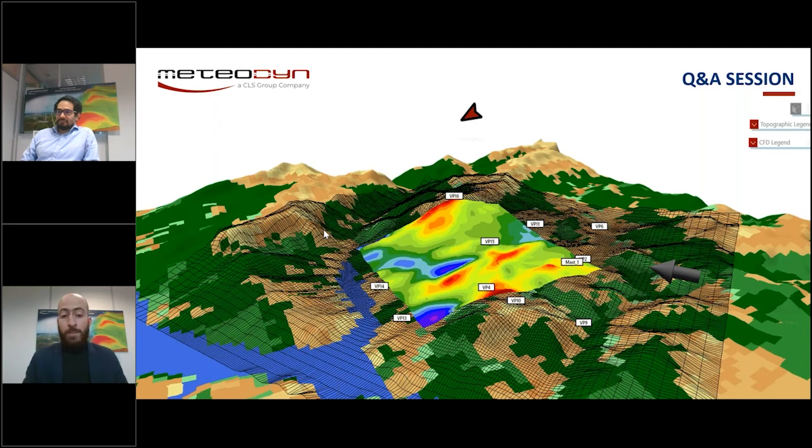So the wind turbines are represented by points, okay, or profiles, okay, so a segment of points, using this during the CFD computation, and then during the synthesis, we use analytical models, okay, to simulate the wake effects. So, for example, the Jensen model, or more advanced wake models like the large farm wake effect model. Okay, but with this version, we do not use the actuator disk.